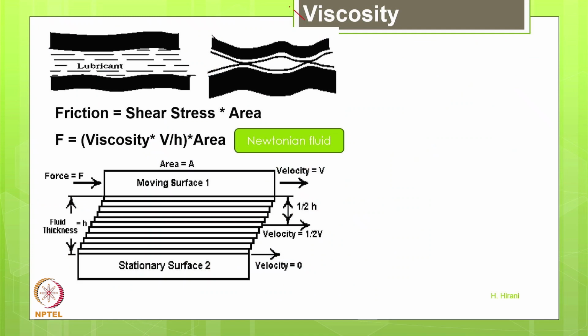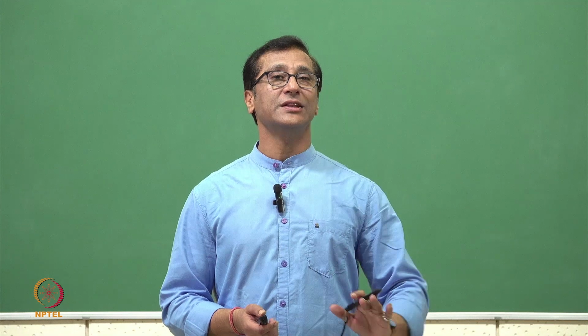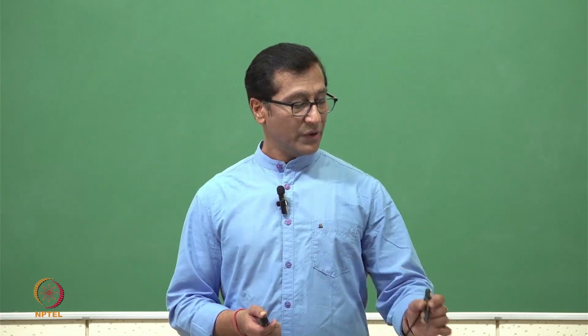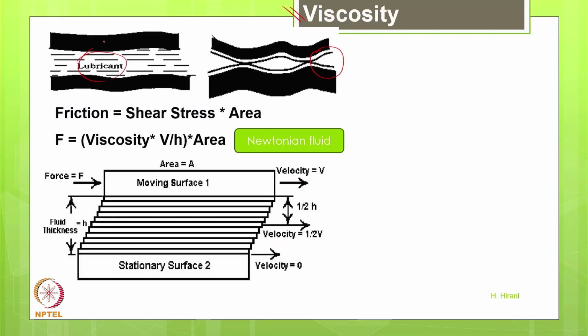Now coming to the viscosity point again, as I mentioned earlier, we require boundary additives to be mixed, so that asperities, even in case they try to touch, glide, really slip, and become a slippery surface. While in thick lubrication we are able to separate them. Naturally, when we talk about the friction force, we need to see how we calculate it. There are a number of theories. The simplest is to think about the shear stress in a liquid and multiply it by the area.